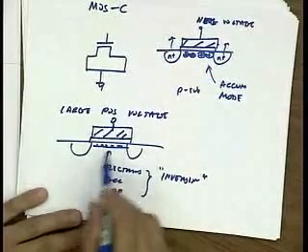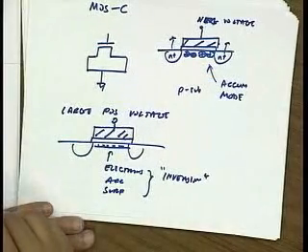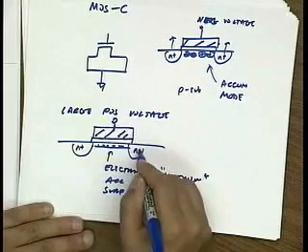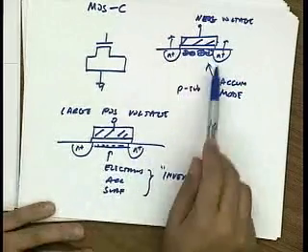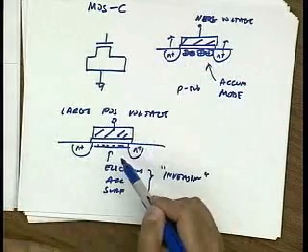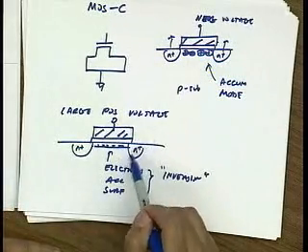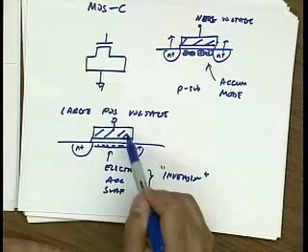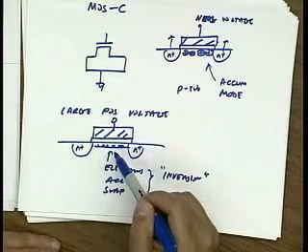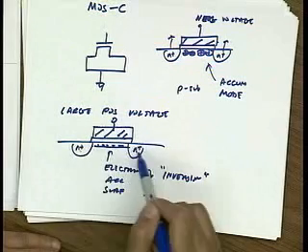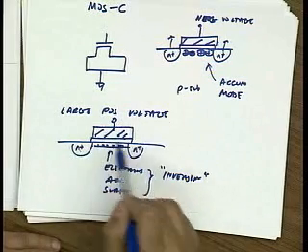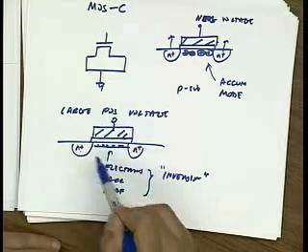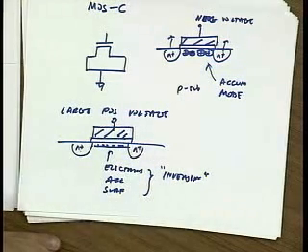And again, this looks a lot like a linear capacitor. Now there's an issue here with frequency because even though there's lots of holes around, electrons are only generated thermally. So if these contacts are far away, this wouldn't be a very good high frequency capacitor. But since I have contacts that are close by and they actually form a continuous channel here, there's plenty of electrons that can come in and form a capacitor.